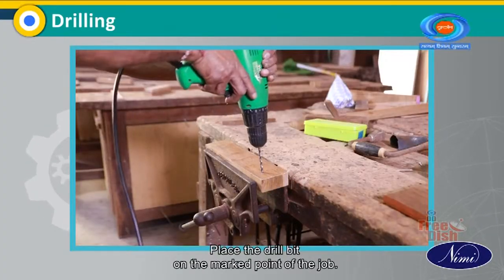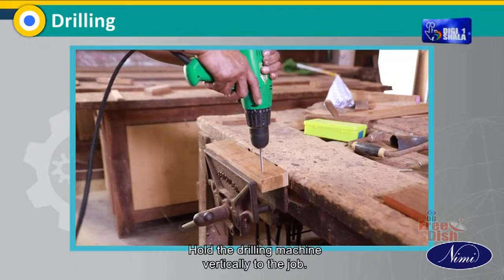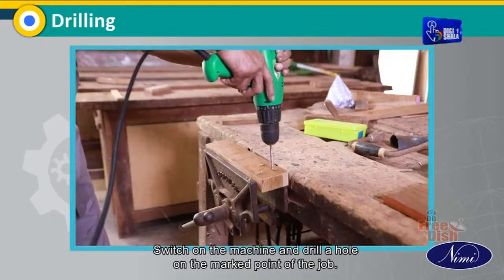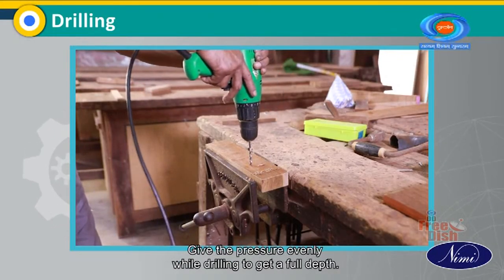Place the drill bit on the marked point of the job. Hold the drilling machine vertically to the job. Switch on the machine and drill a hole on the marked point of the job. Give the pressure evenly while drilling to get a full depth.